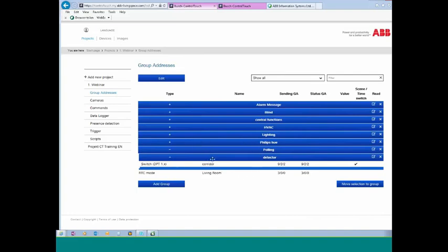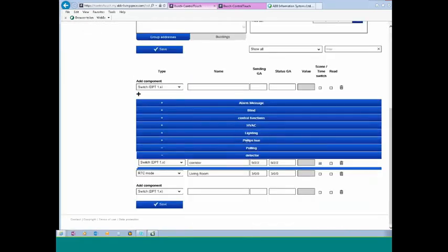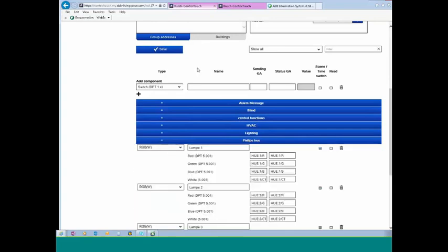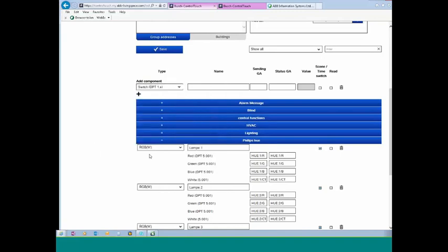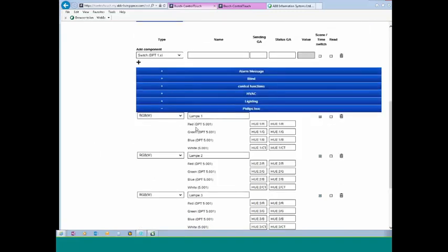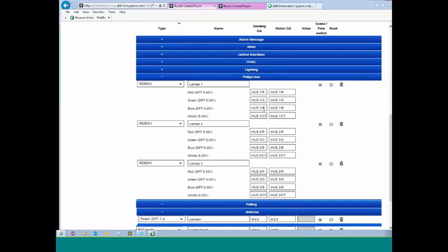What you can do is manually add, as I did here, a new structure called Philips Hue, and I added RGBs and gave a name to say I have 3 lamps, lamp 1, 2, 3, and I create manually more or less a virtual group address like hue, 1, 2, 3 for the lamps and RGB for the colors, and CT if your LED supports color temperature.